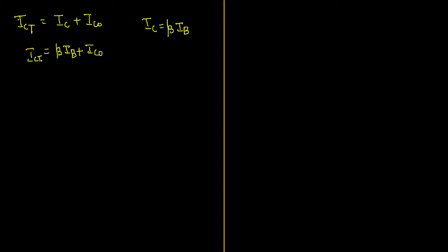This is the total collector current. The alternative way to write down this current is total current. Collector current can also be written in terms of emitter current. How should I write this sir? You might have read these things. IC equal to alpha times of IE. சரி, என்ன சார் இவ்வளோ நேரமாக collector current approximately equal to emitter currentனு தானே சொன்னேன். You have to observe that word. I wrote collector current is approximately equal to emitter current. Then what is the exact relation? It is exactly equal to alpha times of emitter current.